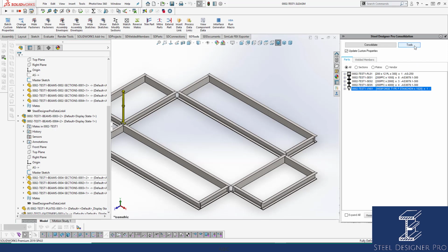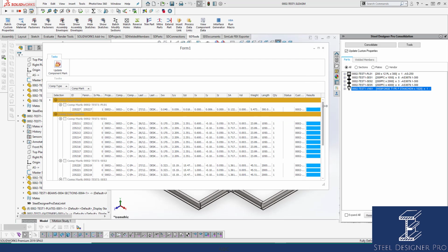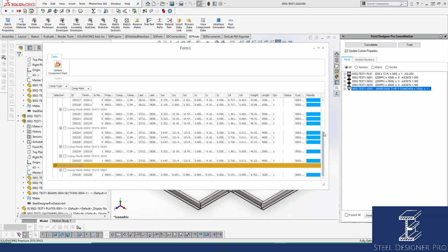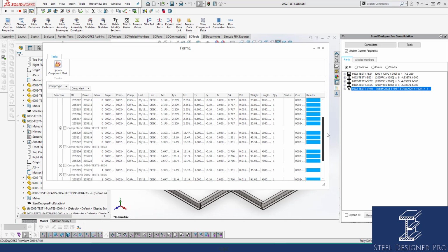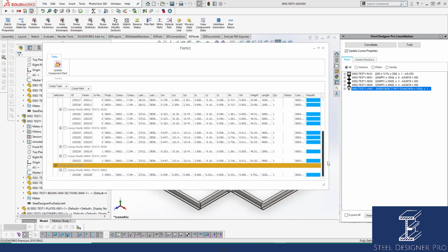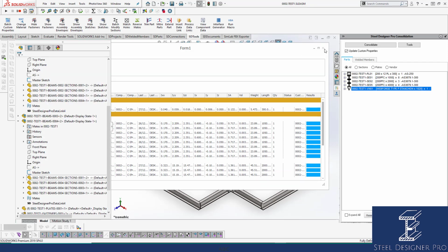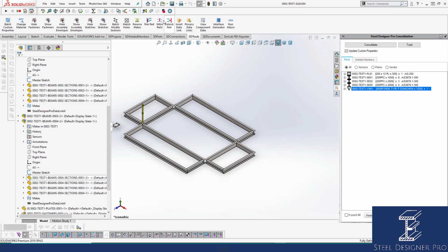And to do that, you've got to go to the tools. Our little tools interface here tells me that all my marks are matching the database, due to the blue lines. The blue line tells me that that mark matches. But if you're not 100% sure, just go update component mark and that will update all of the marks throughout all the components.